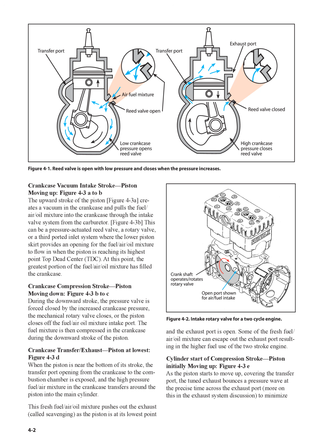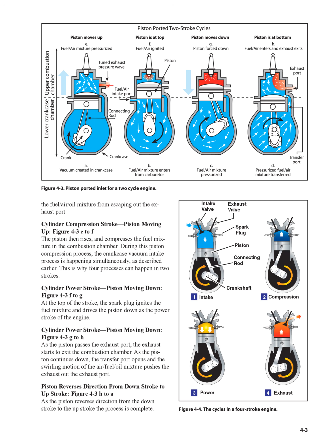As the piston starts to move up, covering the transfer port, the tuned exhaust bounces a pressure wave at the precise time across the exhaust port. More on this in the exhaust system discussion, to minimize the fuel/air/oil mixture from escaping out the exhaust port.